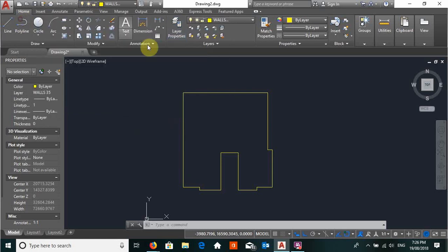So for those that know a bit about building, you'll see that this plan in your set of drawings actually represents a brick veneer house. So we have the outer layer of bricks, then we will offset that by 110, which is a brick size, and then we have a cavity of 40, and then we have a timber stud wall, which is represented by an offset distance of 90.